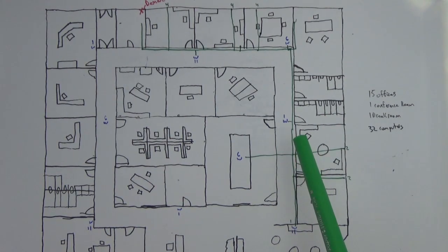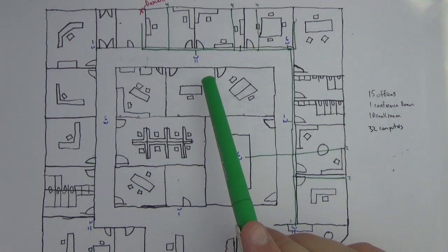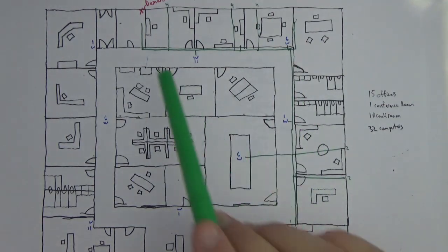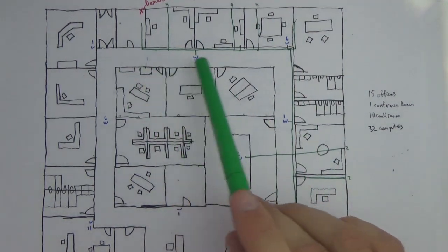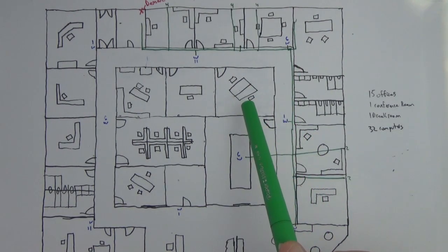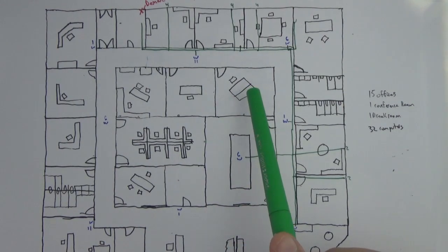Okay. And again, I want to group my cables together. Now, there are pros and cons to grouping cables together. The pro is it's a lot easier if I only have to clear this one path and run all my cables along it. That's good. The downside is if these are all electrical cables, the more and more cables I get bundled together, the more electrical interference I'm going to have, the more crosstalk. So I want to be careful.